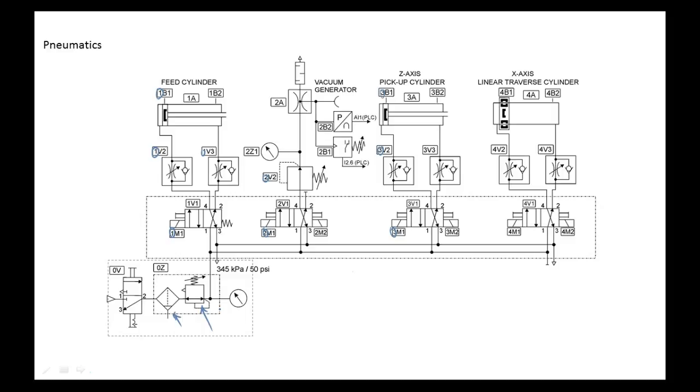But the problem you have is people think about checking to see if the electric power is there, and they forget to check what? The fluid power. If nothing moves, and they're over here taking voltage measurements, and they skipped over one of the basic rules before they take any measurements. One of the first, within the first 3 steps, is to verify what? Verify power. All power sources. All sources of power.